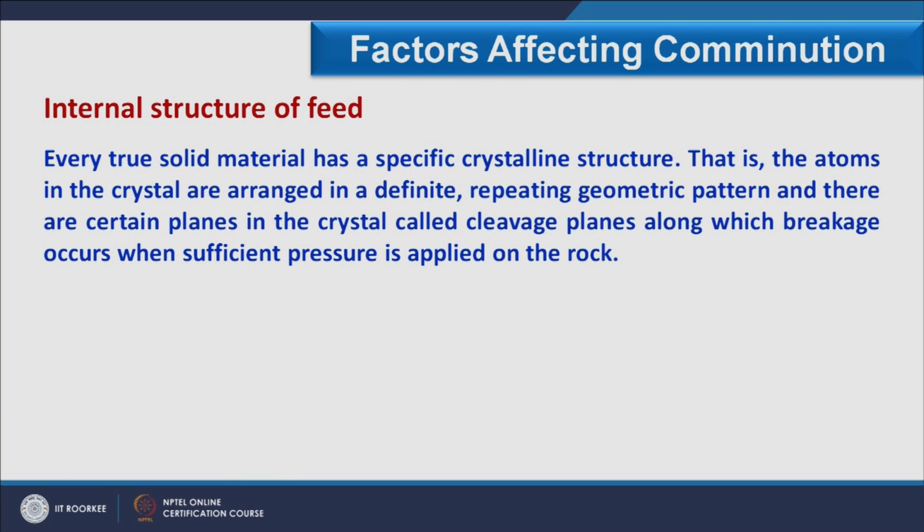To consider an example, if I consider mica, it is basically a simple plate, and when we put a breakage pattern over here, like impact or compression, it will be very difficult to break from this side. However, when we put any force from this side, it will be very easily taken out. So, what we have to do, as far as crystalline structure is concerned, is that the cleavage planes should be targeted first, as far as breakage pattern is concerned, to break the feed.